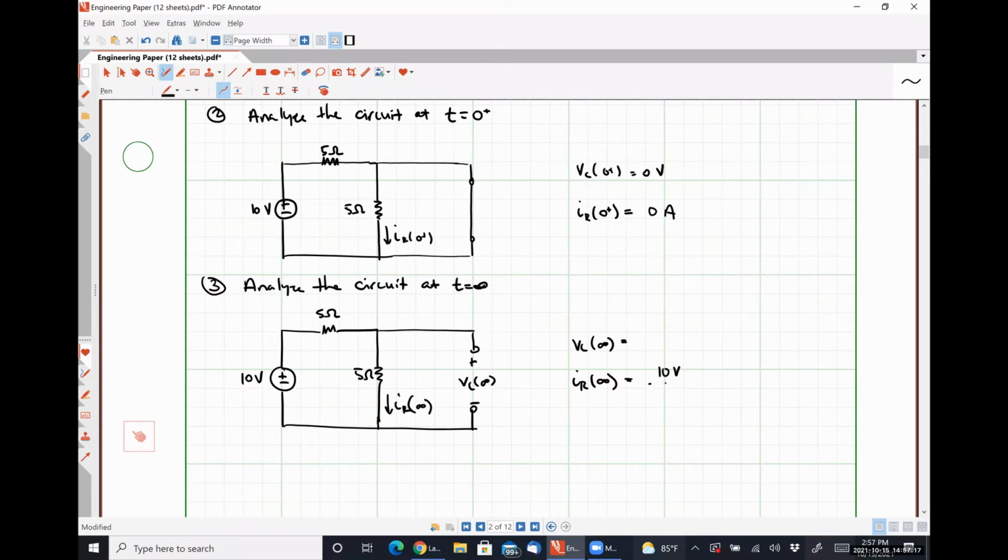So 10 volts divided by 5 ohms plus 5 ohms is equal to 1 amp. I agree wholeheartedly, right? So all the current that leaves the positive polarity terminal of the voltage source has to flow through that top 5 ohm resistor, and then none of it can branch off and flow to the right through the open circuit, gosh. So all of it must flow down through that middle 5 ohm resistor. So we have 10 volts over 10 ohms is equal to 1 amp.